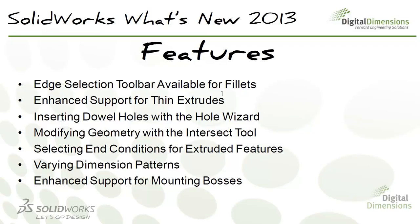Next I'm going to be going over the new enhanced support for thin extrusions. This works on boss and cut extrusions, and this is going to allow you to use multiple open contours for thin extrusions. I'm also going to be going over the new dowel hole option in the Hole Wizard for normal through holes. Next I'm going to be going over the new feature called Intersect.